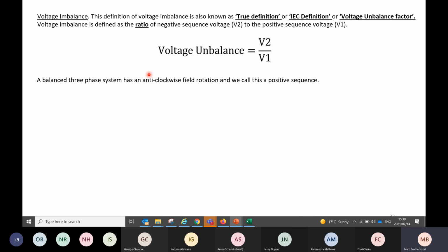Too many devices are being used in the building at once on single phase. Even too much fluorescent lights suddenly get switched on. There might be 150 lights that suddenly switch on. They create a huge voltage drop and a lot of harmonics in the line.